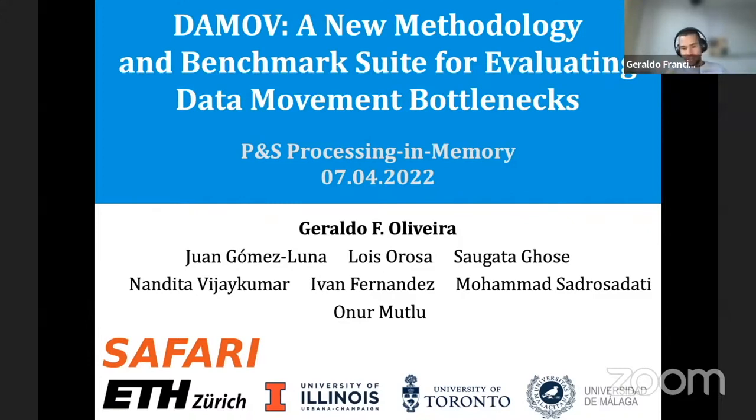And there is, of course, some caching system being employed to figure out if a particular piece of data can be accessed by a particular PIM core, because employing the same coherence protocols that we have in the CPU, like directory-based or snooping-based, in the NDP system is quite costly because of the area limitation you have for designing a network. So there are these two problems, both from the host to the PIM cores and also across the PIM cores themselves.